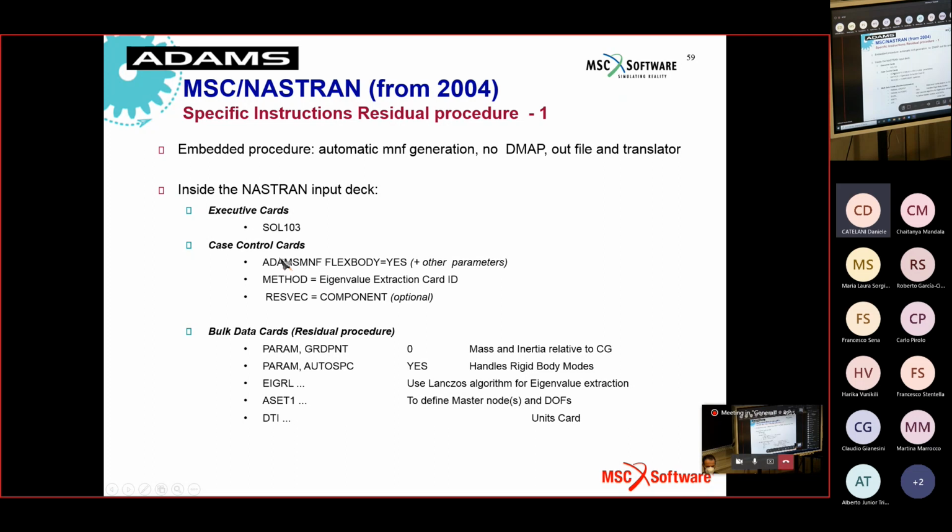So the results of this analysis will be written in the standard Nastran files, F06, F04, log, XDB, etc., but also in a file called MNF.